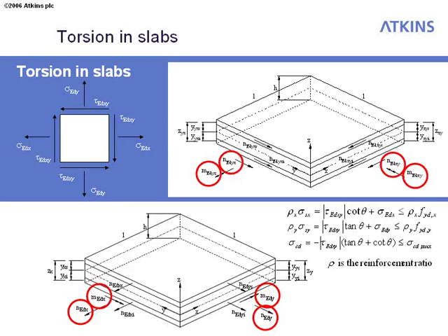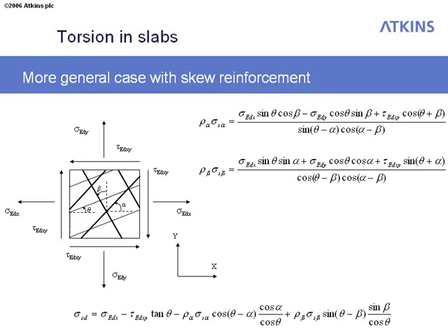I'm not going to go through any of this now. There is a session on sandwich models later on, which we may or may not have time to do. But this is really just trying to describe a way of turning the forces in a general in and out of plane stress field into simply in-plane forces, and then we can derive the reinforcements from a set of equations for the in-plane forces. And it gets quite complicated when you've got skew reinforcement.